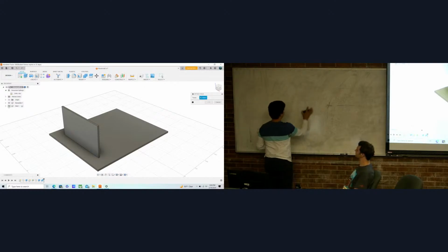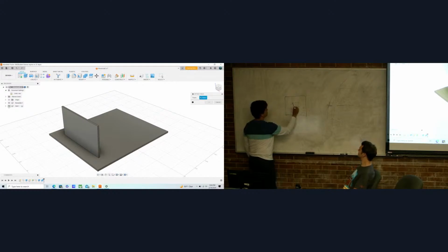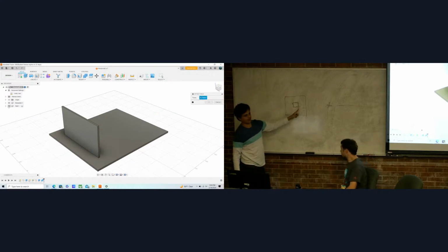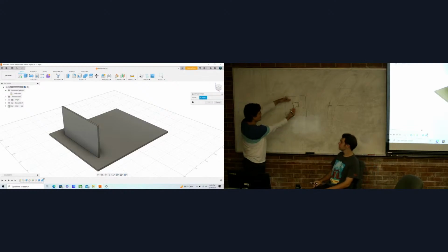So to put that in terms of a piece like this that I'm 3D printing, and inside of this piece, I have a hole. This is the imaginary line of CAD where the hole is. When I 3D print it, the actual line is going to be here. And so this hole is ever so slightly smaller than what the hole is in CAD, right? Obviously, I'm zooming in here, so it's exaggerated, but that's the concept.